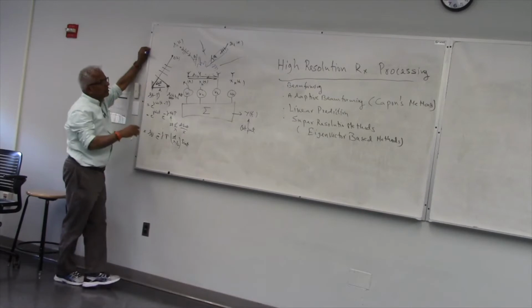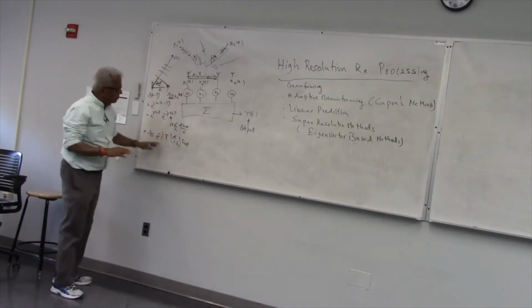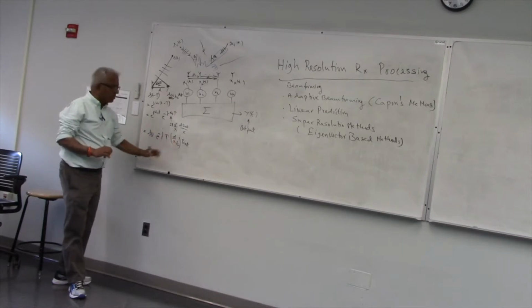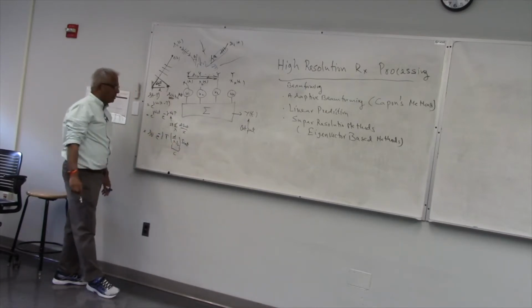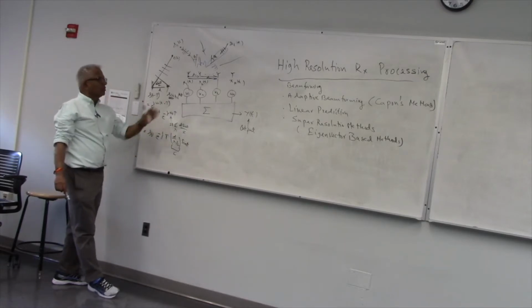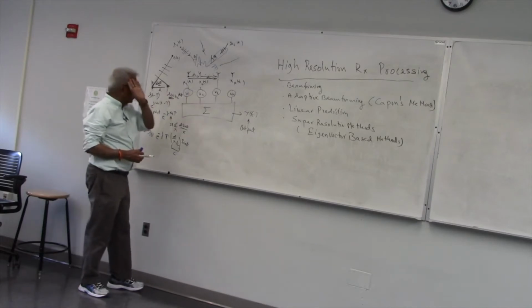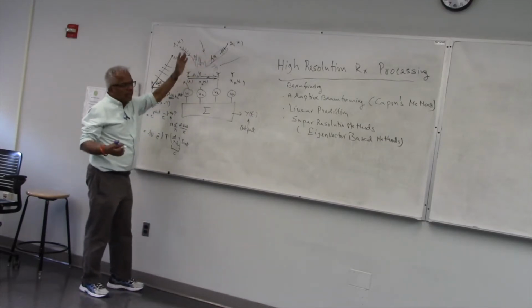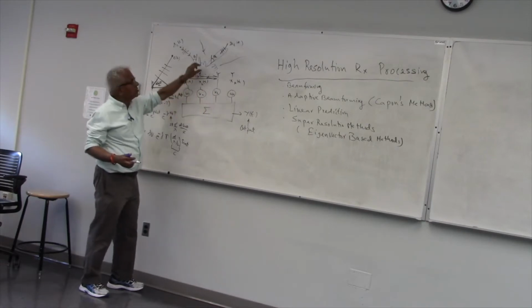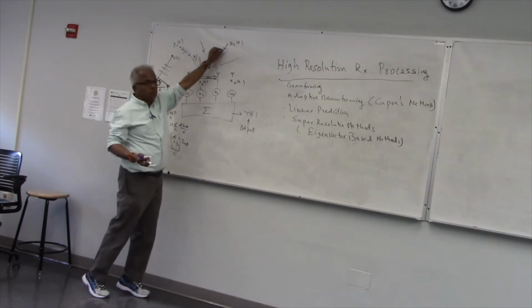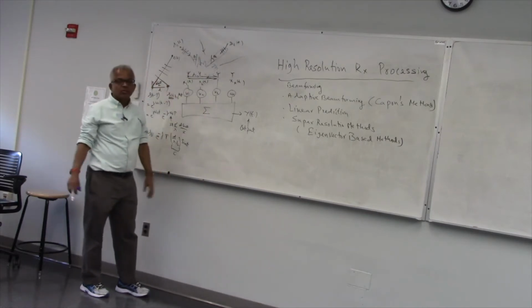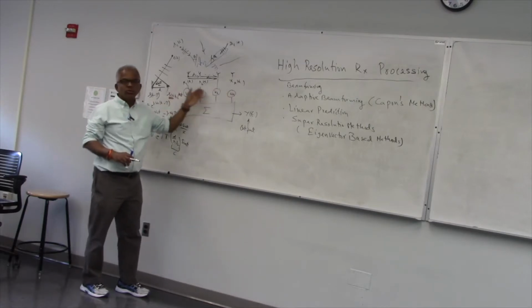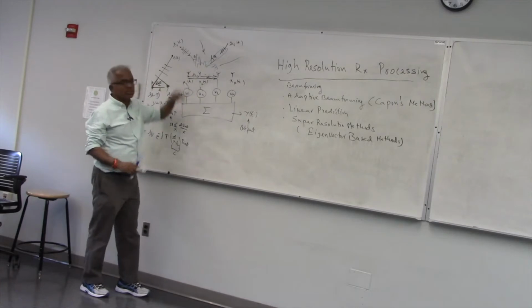And so the question is, if you have an interference, and I showed you if you use this simple phase delay, so here the phase delay is depending on the sensor, you're advancing the phase by the complex conjugate of this. So if this is a numerical value i, in other words, it's multiples of lambda by 2, then that becomes uniform phase shifting or steering the array to a particular direction. So essentially you come up with a beamform. So the idea of putting weights, you could say, is to form a beam. Then you get the idea. You want the main beam to be as narrow as possible and the side lobes to be as low as possible. So that itself has lots of papers on it.